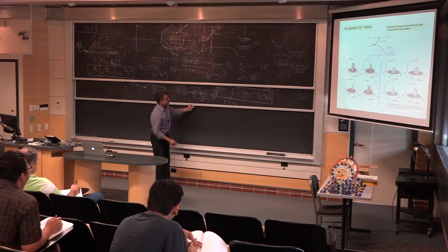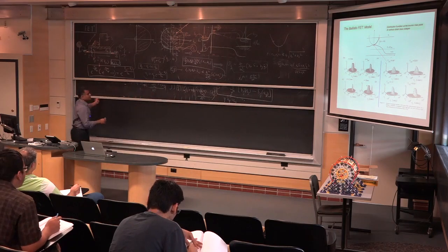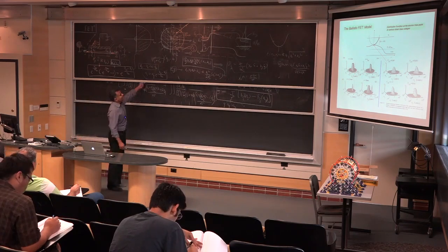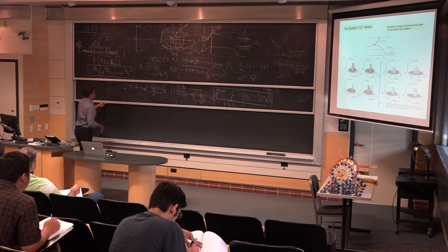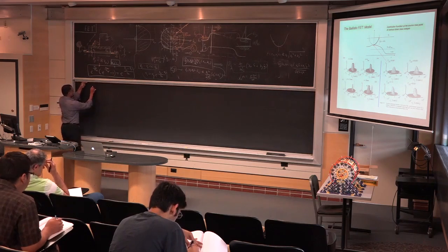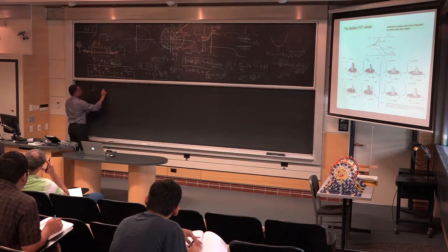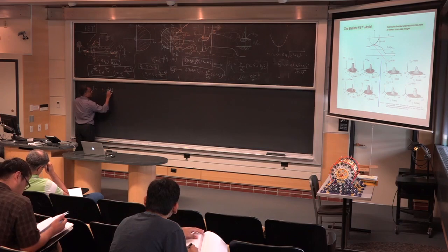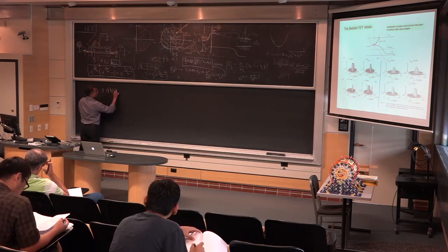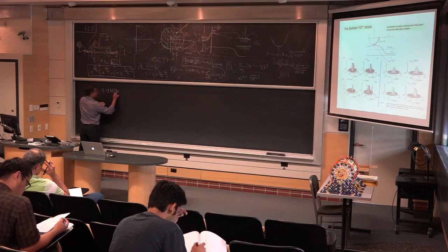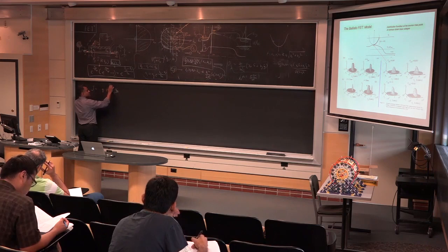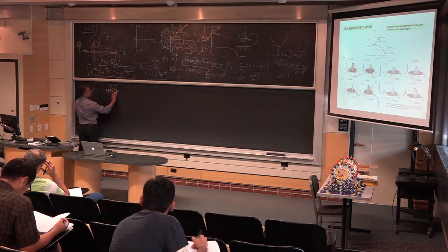And let me write that down in a little more detail. So the net current, I'm running out of space here and time. So, okay, let me rewrite that. So the net current in the ballistic FET will be Q times n quantum, which we had derived in the last class, which looks like the quantum capacitance, which is Q squared times the density of states, times the thermal voltage over Q. So n quantum was CQ times the thermal voltage.